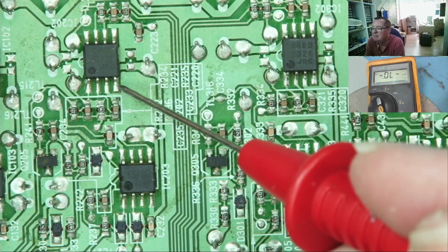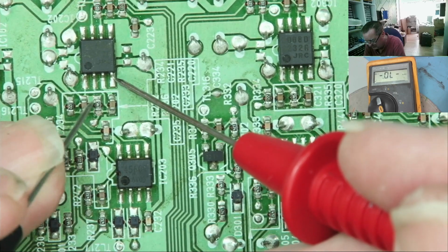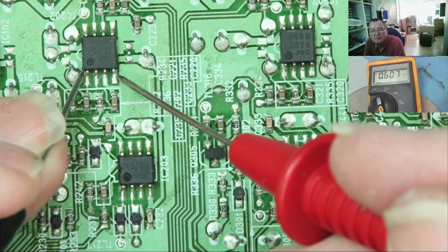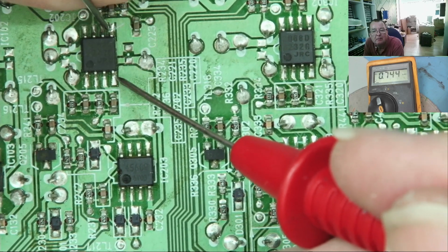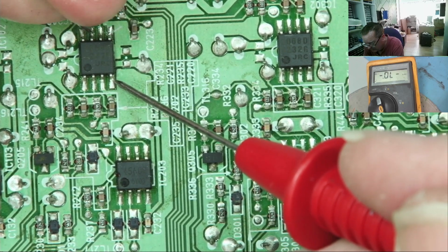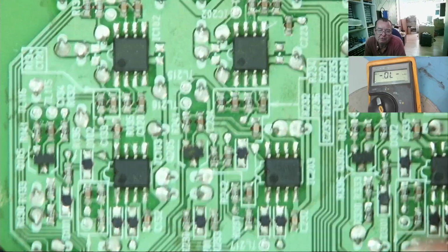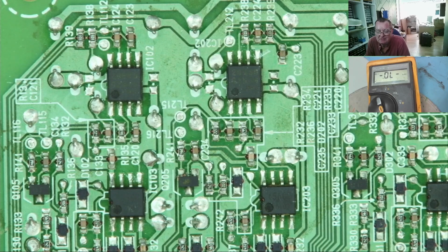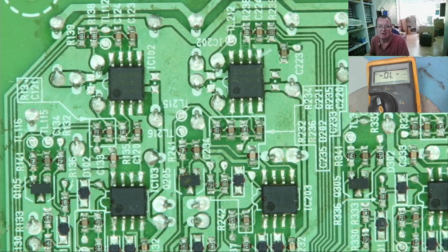Here's another chip of the same sort as that one. Okay, 469, 603. So again, this pin reads a bit lower than the others, and then on the other side, reads a bit lower. Okay. What you're looking for here is drastic differences or shorts. Which I guess is a drastic difference. Shorts and open. So that's a quick and nasty way to test op amps, but it'll probably get you by in well over 90% of cases.